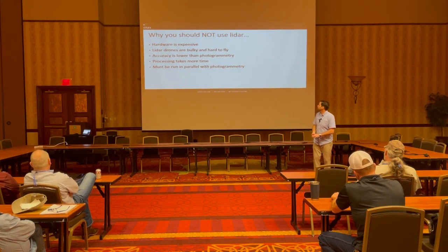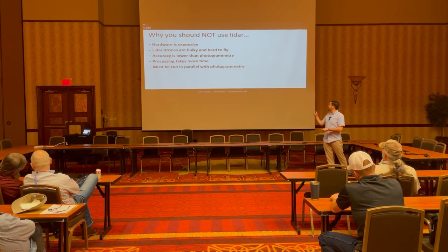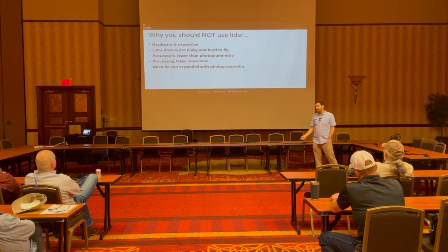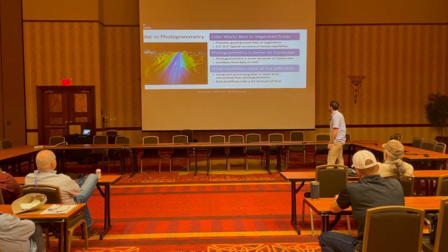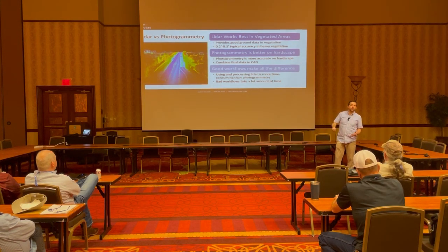I've already gone over this a little bit, why you should not use LiDAR. It's pretty expensive. It's bulky and hard to use. It often takes more specialized training to fly the drone. But it does make sense, like I said, if you're doing topo, if you're doing vegetated areas. But most importantly, I think, is, again, good workflow is going to be what really makes the difference.